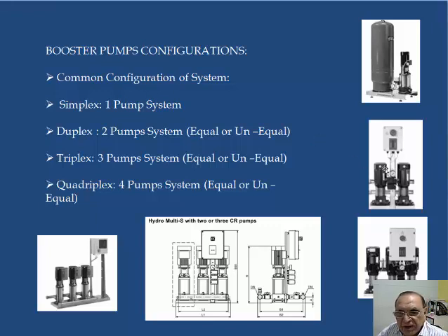But the standby pumps, when we take for this, we should go for a larger size which can meet at least 70 to 80% demand. And that is how the configuration of the different kinds of systems are made.